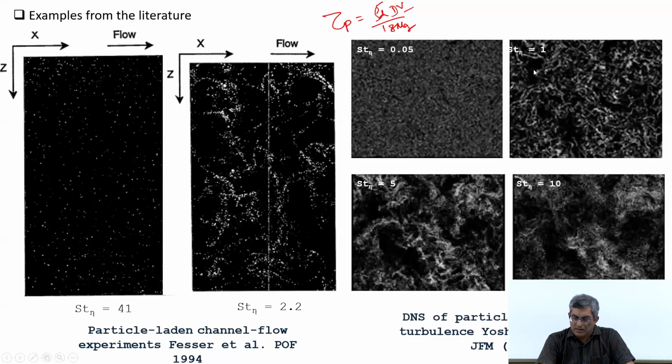Also, you see that for different Stokes numbers, even if these are all of order 1, the behavior of particle clusters, or qualitatively the length scale of the particle clusters, is not the same, it changes. So, this means that the clustering behavior changes with Stokes number. It is not like for all Stokes numbers, even if it is of the order of 1, the behavior will be the same. No. Yes, we can say that for all cases we see the preferential accumulation effect.